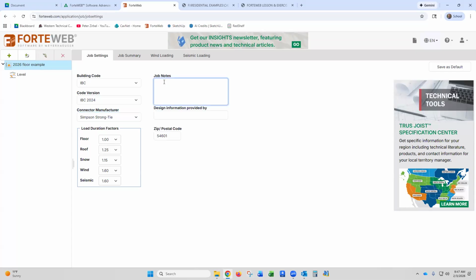If you're in Wyoming designing a house and it's super windy all the time, you get that number up. Well, the code might actually tell you differently, but the reality is you're going to have a wind load based on the code. The fact that it's super windy all the time probably isn't going to impact your building, because it's not like buildings are designed for a 20-mile-an-hour wind versus a 10-mile-an-hour wind. They're designed for 80 or 100-mile-an-hour winds, like in a tornado or a thunderstorm. Does that make sense?